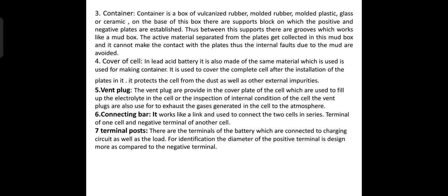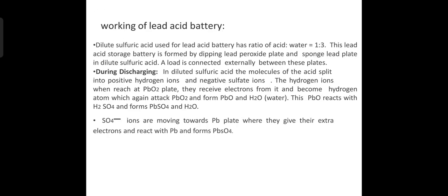Next are the terminal posts of the battery, which are connected to the charging circuit as well as the load. For identification, the diameter of the positive terminal is designed to be larger than that of the negative terminal. This is the construction of a lead acid battery.